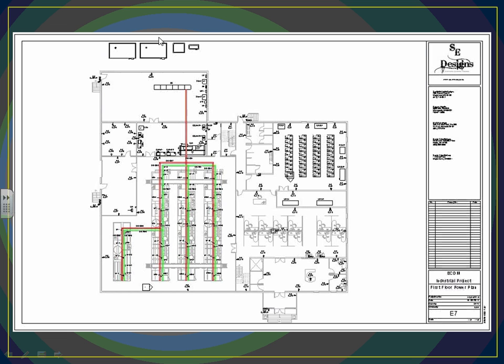So the building, we're backing up the building by generators, 100%. We have money to spend, like I wish we had when we were doing a project. So you end up bringing generators outside. The voltage to this building is 480/277. We have a couple of transformers and a termination box in the back, and we're bringing the power in here.